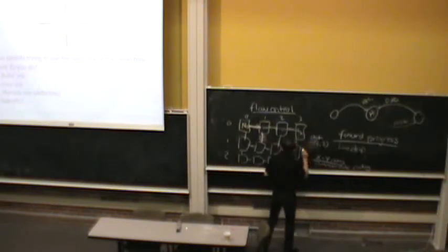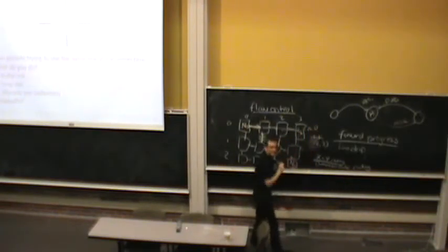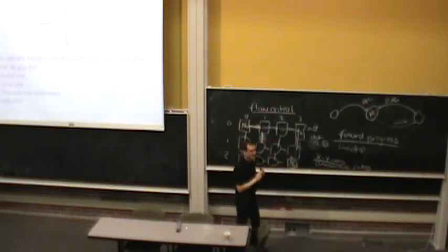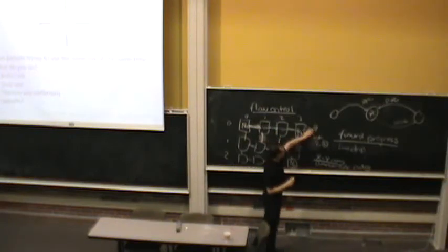Yeah, destination is 2, 3, and this router itself is at 0, 3, right? So what the router does is it simply compares the y dimension to the destination y dimension, and they're the same. So now I should send it down this way. That's how the dimensional order routing gets implemented. So you can see how simple of a routing scheme this is.